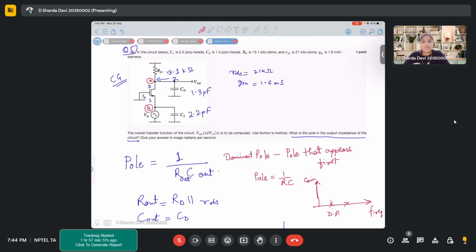But this capacitance, ma'am, is inversely proportional to the distance between the two plates. Correct? That is always there. So if the depletion region decreases, the distance between the two conducting materials decreases, so the capacitance should increase, isn't it? Yes, it will increase.